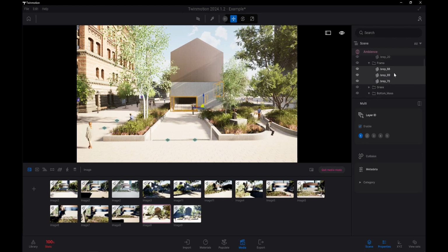So it's really important that you give these material IDs, okay? And just to be on the safe side, even on the layers, I enable it on the entire layer. But I go in here and select this, enable. Okay. Oh, wait. So for grass, I don't want that. For grass, we'll make that a 2. Okay, that's important. But for buildings, so anything related to buildings, like top mass, bottom mass, window, frames, I make that a material ID of 1.